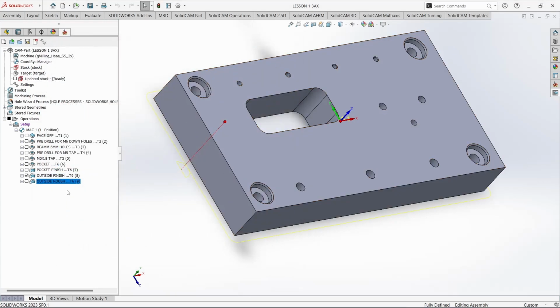Right, let's say if you move something and it's not in the order that you want, you just click and hold it, and then drag it down. Therefore, your toolpath will stay down there. Now, rough, rough, pocket rough.